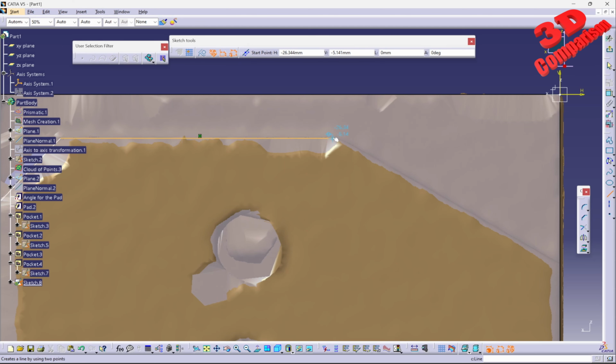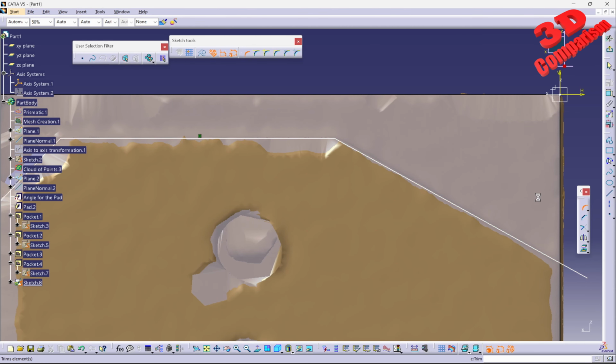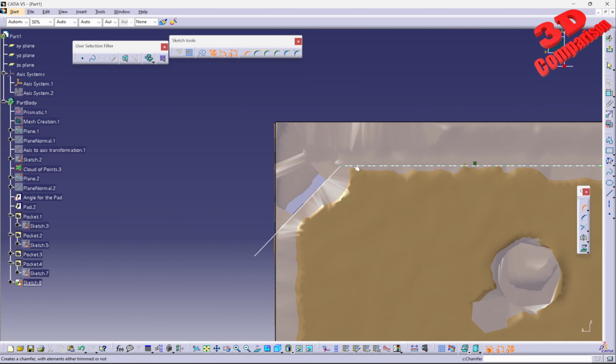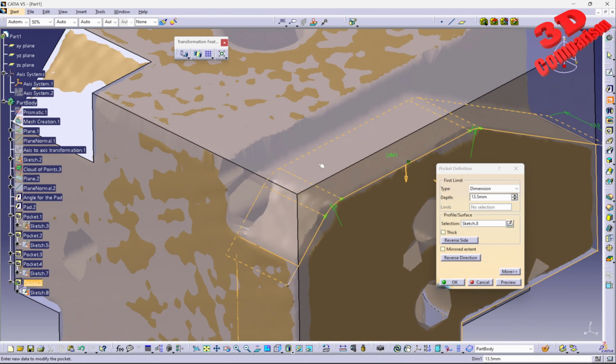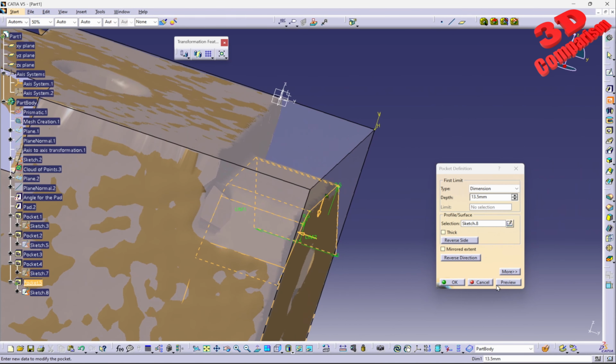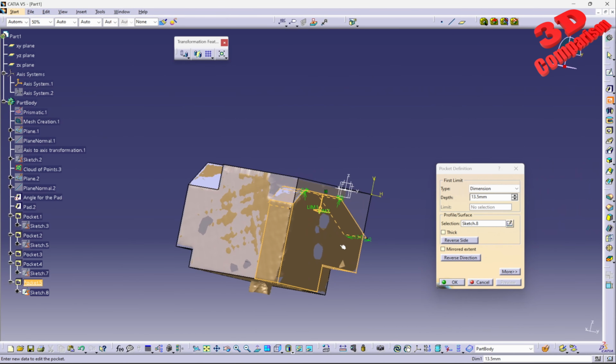We can add some radius over here as well, directly within the sketch. So let's add those. Maybe a radius of 5. Do the same radius over here, so 5. And again, we can do the extrude cut. In this case, with 30 millimeters, it will go like that.